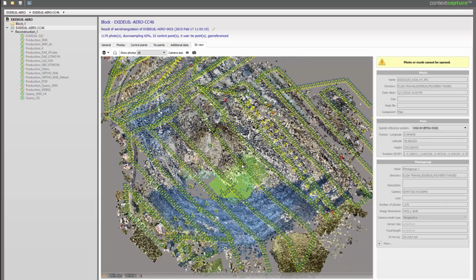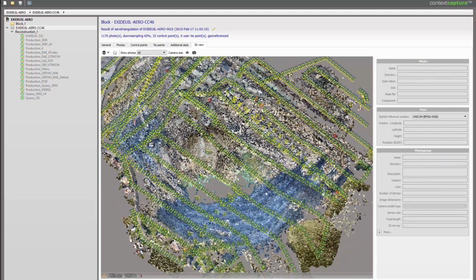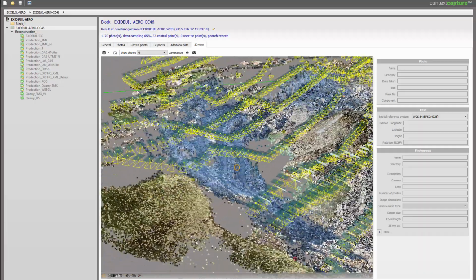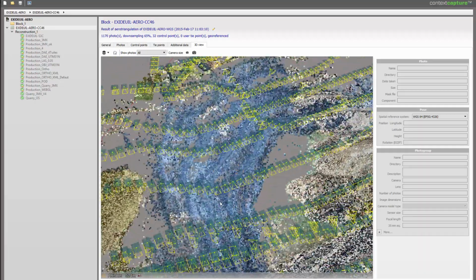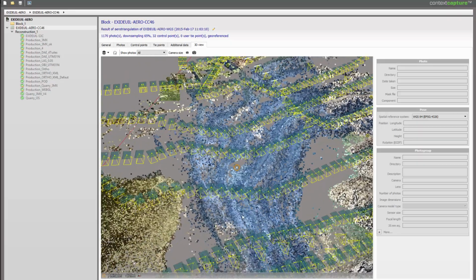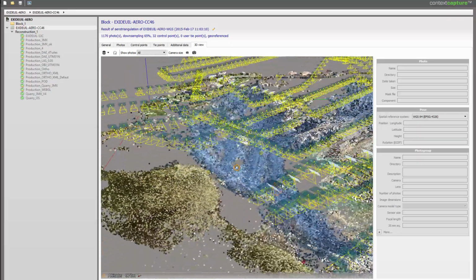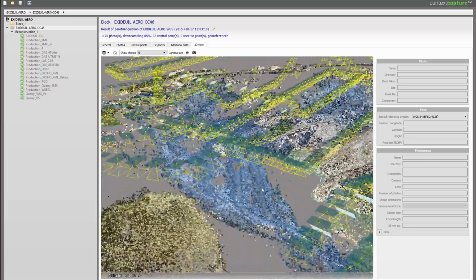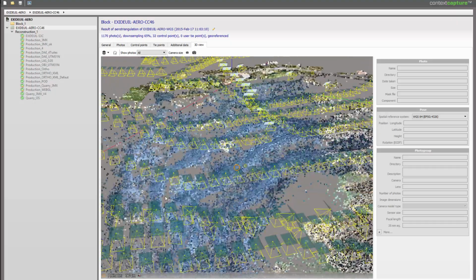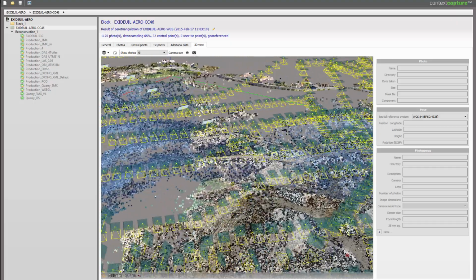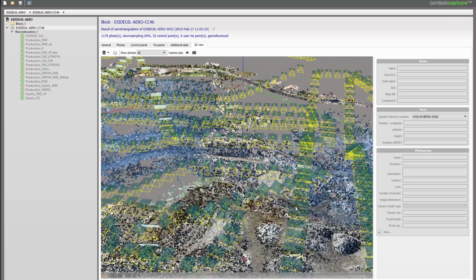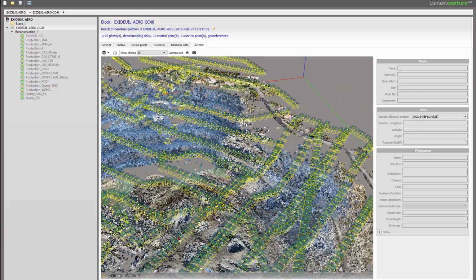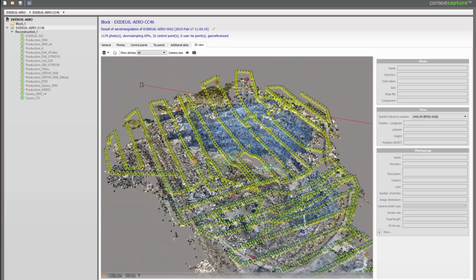The pilot ensured enough overlap between the different photos, but also set the altitude of the drone to best follow the distance from the object, to keep a constant resolution in the photos. Indeed, you have to account for the difference between altitude of flight and distance from the ground.